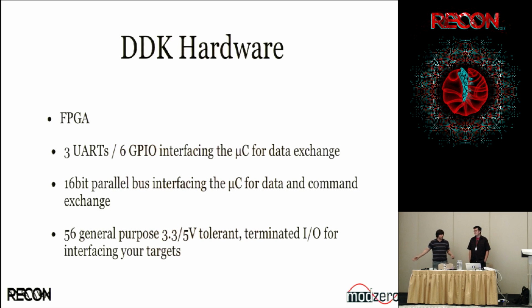Actually, during the training, for example, everyone wrote a UART in Verilog. And I think if you ask the people who took the training, they'll attest to how easy it is to write a UART on an FPGA. And this is a perfect interface, which is already there on the ARM, on the LPCs. You can clock it up to 3 megabits, and it'll do fine. So that's why we chose that.